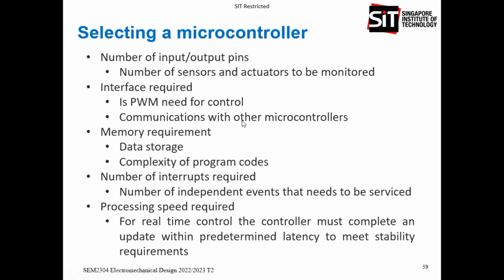Then for memory, let's say for flight control, you need to store a mission. So you must make sure that whatever memory you have is enough. And sometimes, for those that I'm used to working with, I also need to store all the flight control information. It's like the black box on a commercial aircraft. So for drones, if I fly, I make sure I have a black box in there also. So if something happens, at least I can do some forensics to determine what went wrong. So you must make sure this microcontroller can support external data storage as well.